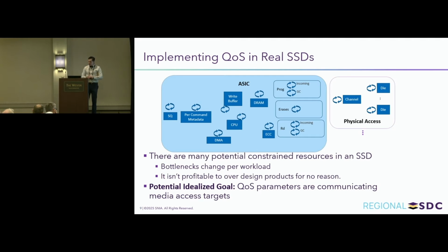Something that I like to point out is that in one SSD, you might have NAND-gated behavior in fully read workloads. And likewise, in a full write workload, you also might be NAND-gated. But frequently, in a mixed workload, you'll find that you hit a DRAM bottleneck, or maybe a NAND channel bottleneck. You'll find that you're hitting different bottlenecks at different capacity points, at different read and write ratios, and those dynamic positions of where you're hitting a bottleneck are real design problems.